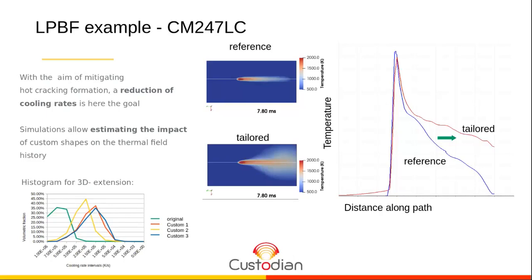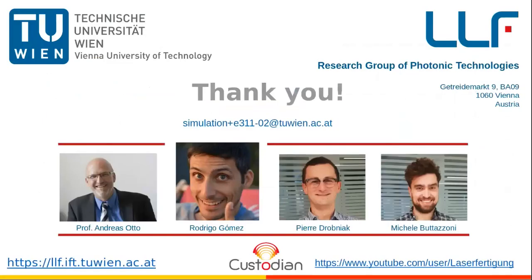We are evaluating a similar plot of the thermal history of the maximal cooling rate experienced by every single mesh element in the 3D volume. The idea is to bring these values towards the minimum values of the maximal experienced cooling rates in order to reduce these solidification problems.